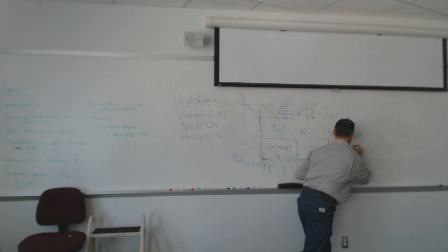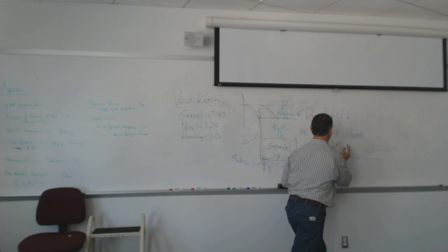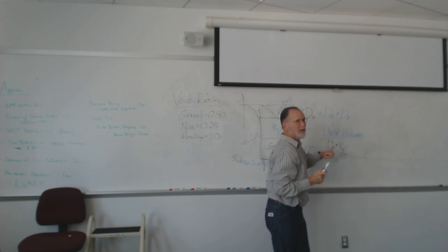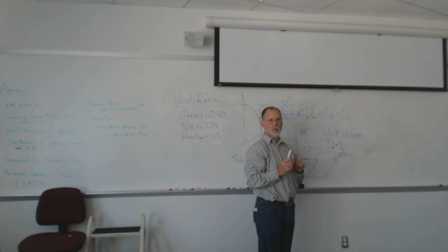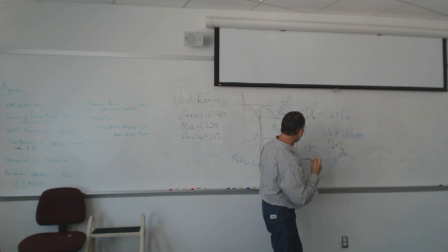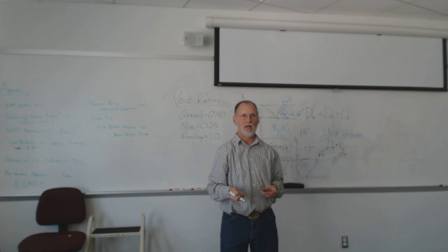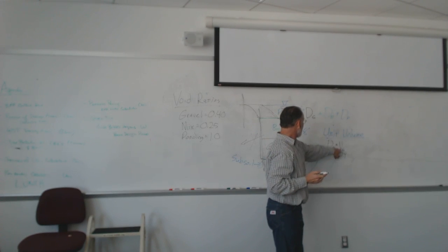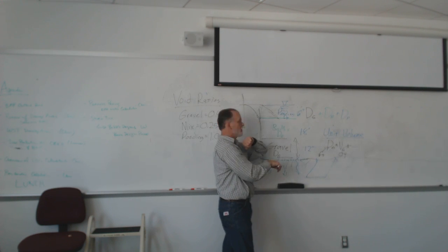So my depth here, I'm sorry, that's my depth, that's my void ratio. That's right. So it's by the surface area that it's on, and the surface area is 1 square foot. Again, picture this 1 foot square column, like a very tall ice cube tray, times my void ratio. This has to be in feet, because we want everything to end up in cubic feet. So that's how much water I'm going to hold in the gravel section.